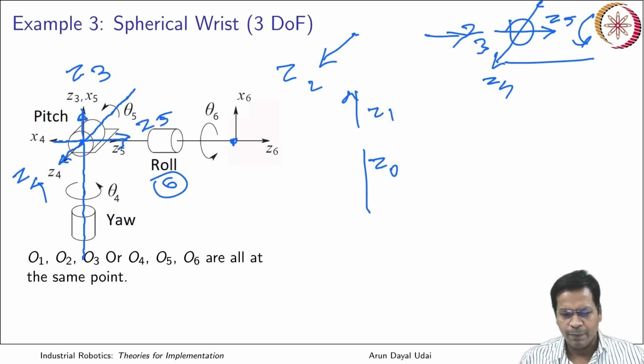Z6. It is nothing but a dislocation of the axis which is here, the 5th axis, exactly that comes here, and there is a distance between these two. So this is your spherical wrist center, and finally this is the distance D6 because it is traveling along the Z axis. So it is D6 that finally ends here. So this is your last frame, that is the tool frame. Okay.